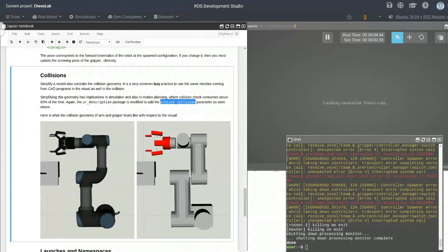So it's up to you to dedicate maybe one morning to generate the basic collision geometry of your robot. You see here there are some meshes, but this is actually how RViz renders a cylinder. In the collision engine of Gazebo, it's using a primitive called a cylinder, which is easier to check for collisions.